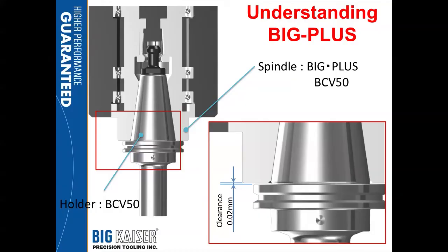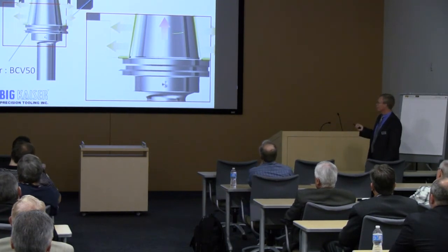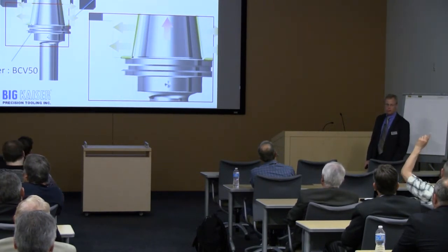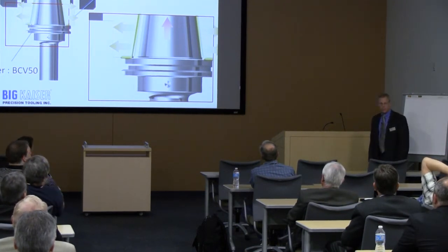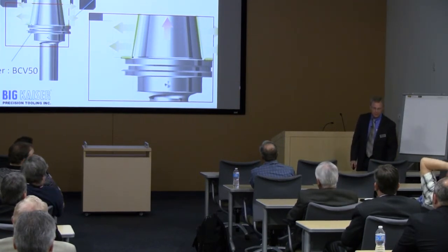So when I clamp, I elastically deform within the limits of normal elastic deformation. And now I bring the tool up that last 8/10 and I get my face contact. But I don't lose the taper contact. That is an extremely important part of the dual contact system. Establishing a taper contact fit first. What happens if there's dirt on that flange and you still have enough taper engagement, but now the dirt's standing between you and the spindle face? You would have nearly the same problem.